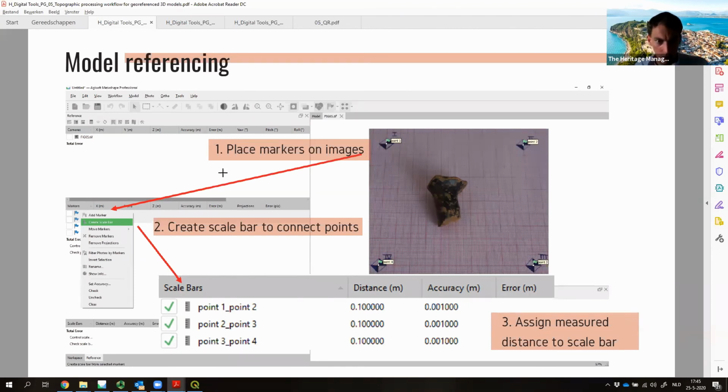So of course, if you are familiar with Pythagoras and you make a physical triangle with a side of 3 and a side of 4, then the sloped side has a size of 5. So you can make any multiplications of these values, and by making a physical frame of these values and using them on site, you can have a very mobile way of working with a coordinate reference system. There's a question probably about it.